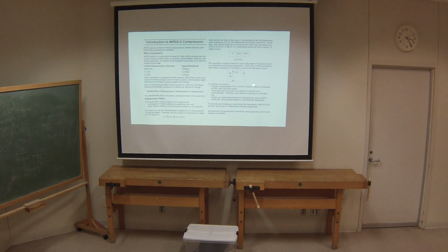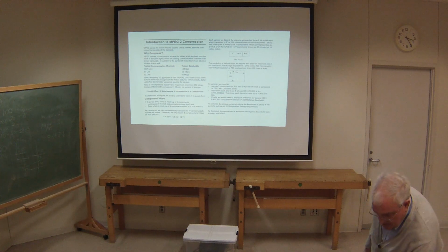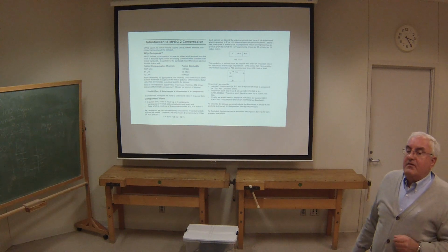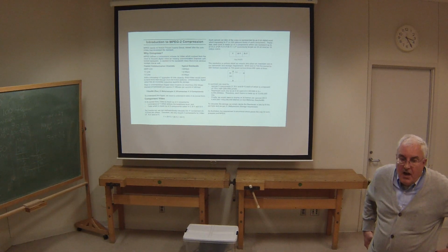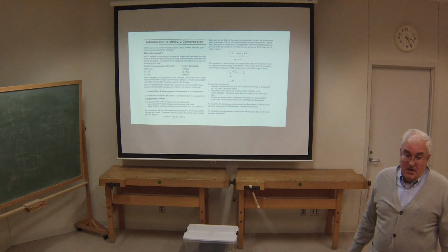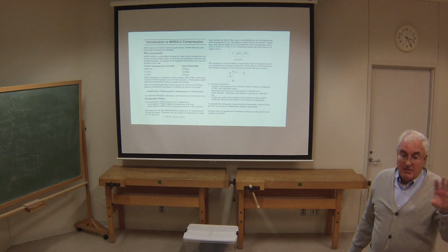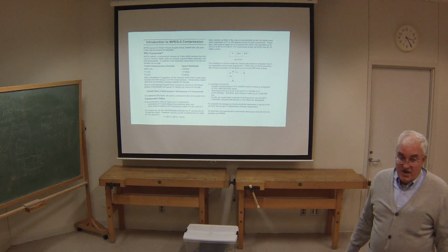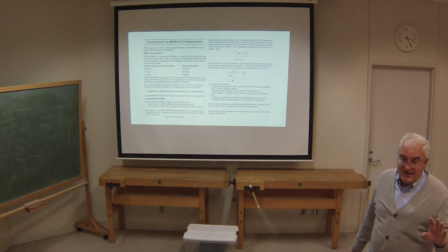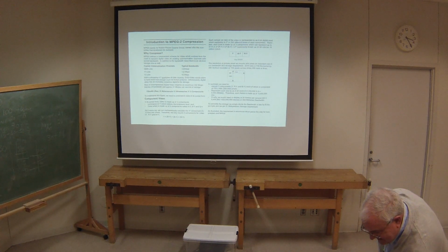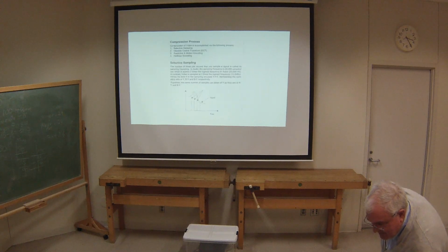Here the example is standard definition, which is 720 across and 480 down. That one, 525 down. Pardon? Wasn't it, didn't it used to have 525? 525 included the blanking area. But if you strip out the blanking area, you're left with 480. So that's another discussion. But yeah, you're quite correct on that.